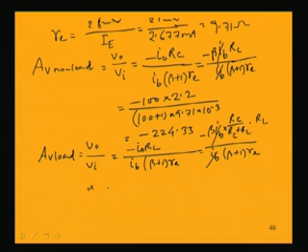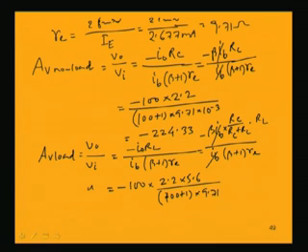So, this value when you put it, it will be equal to minus 100 into RC value is 2.2, RL is 5.6 kilo ohm by 100 plus 1, and RE value is 9.71 into 10 to the power minus 3, and that value is equal to minus 161.06.